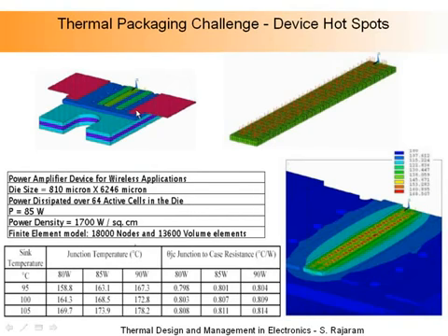And this is a cross-section of a device. Within that device, actually you see these 3 green fingers. Each of these fingers, the size is 810 by 6,246 microns. And on that, you've got 64 active cells as shown here. These are the junctions of the transistor where the transistors are switching back and forth and dissipating the power.